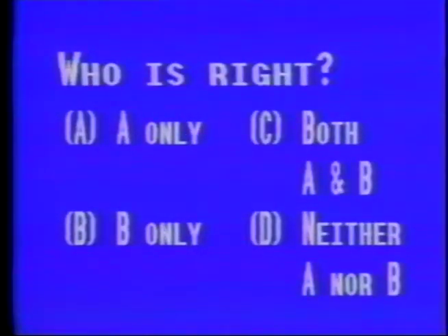A customer states the brake warning light comes on. Technician A says that a faulty parking brake switch could be the cause. Technician B says that there may be uneven pressure in the brake system. Who's right? A, A only. B, B only. C, both A and B. D, neither A nor B.